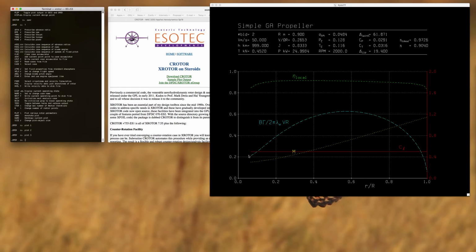Then you actually have your lift parameter. This is essentially your local circulation value across the blade, so this is how you're calculating the lift. Notice that you're tending to get a lot of lift at the outer section of the prop, and that is because you're rotating at a faster velocity. Again, this is spinning as a solid body, so closer to the hub, even though you're spinning at the same RPM, that local velocity is actually pretty low, right?